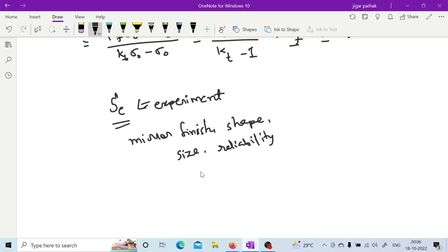And stress concentration also needs to be taken care of. So if you consider all these factors when you calculate your updated or corrected endurance limit, you are going to consider Ka, Kb, Kc, Kd, and correct your calculated endurance limit from the experiment.